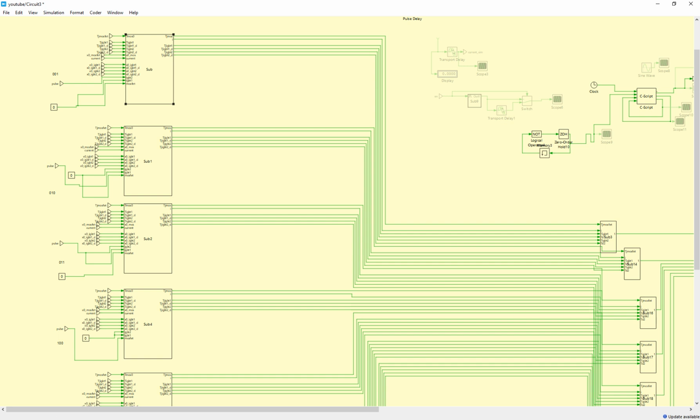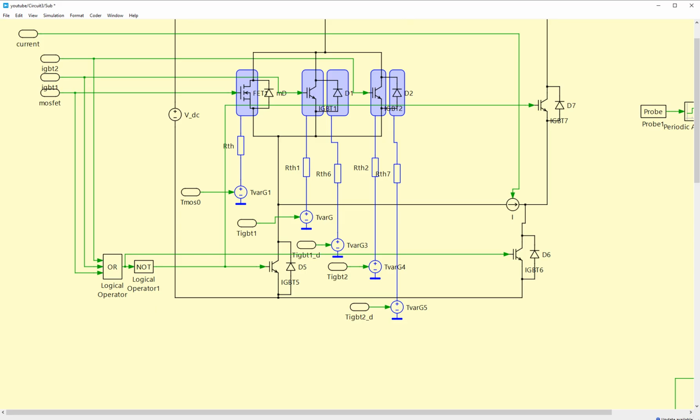If the optimal state for one switching period is this one, you need to feed back the temperature to all other circuits for the next switching period. Through this mechanism, similar for IGBTs and also diodes, I can set the junction temperatures from outside.